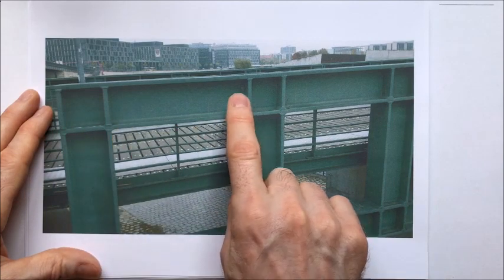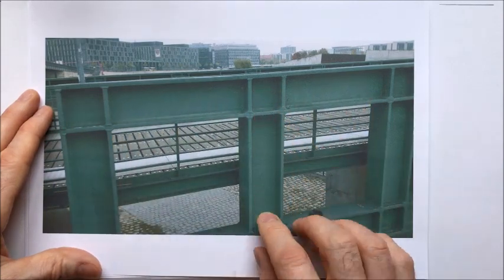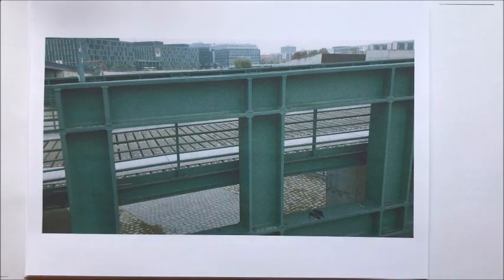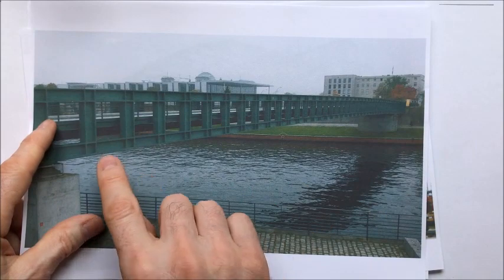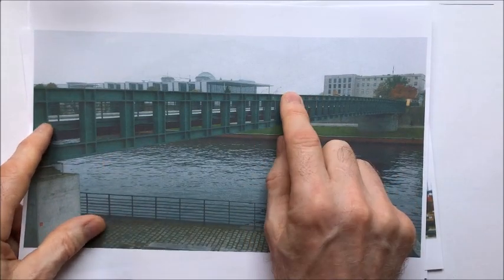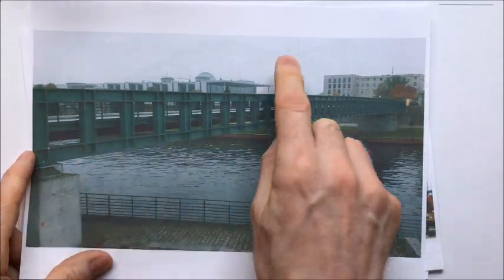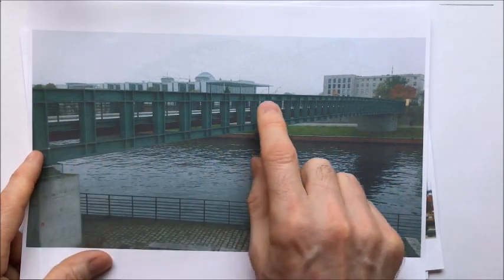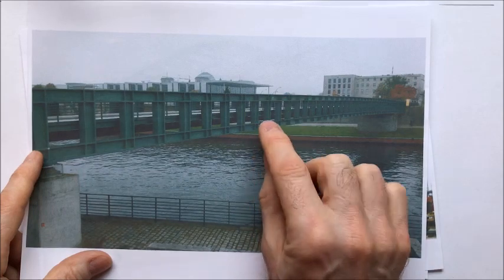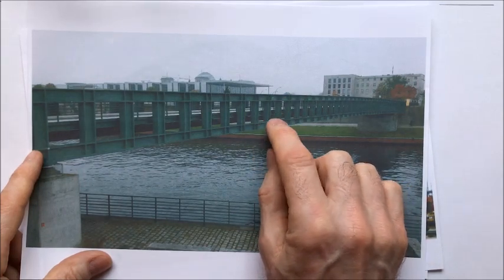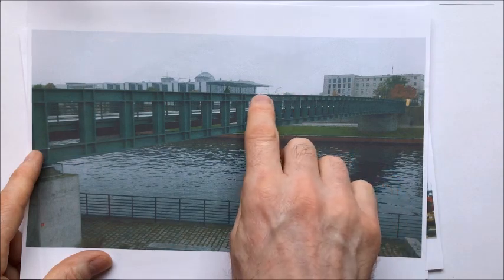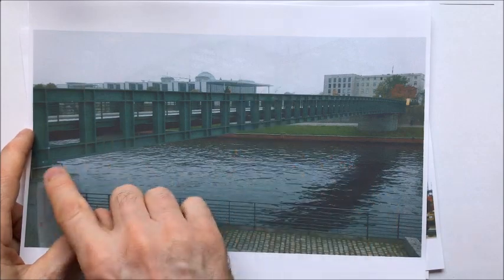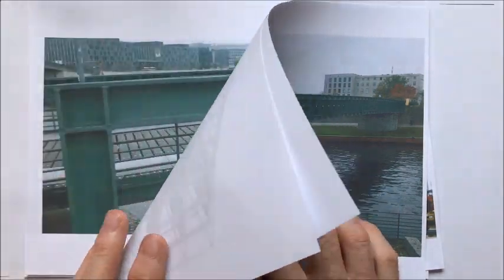You can see that these connections between the top chord and the vertical internal members are moment connections, and that's because in a Vierendeel girder a load that's applied at one point is transferred to the foundations through bending in the members, a little bit through axial force in the members, and also through shear in the top member and the bottom member, transferring these forces from the point of application to the point of support. Great.